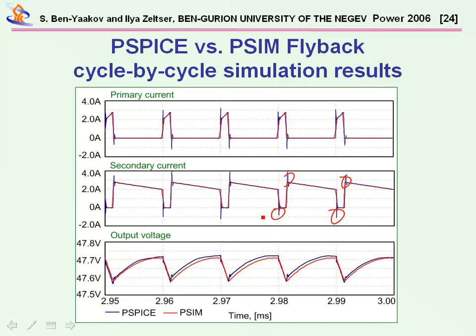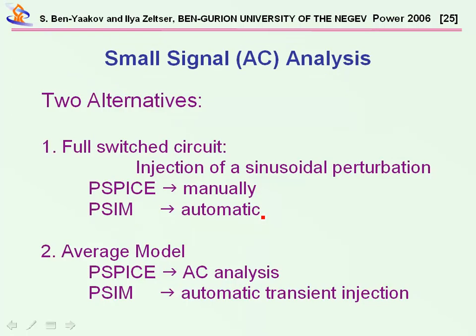On the other hand, if you'd like to look at transitions, rise time or effect of snubbers, or performance of snubbers, then maybe you might have a slight problem. You'll have to decrease very much the step size in order to be able to look at the transition itself.